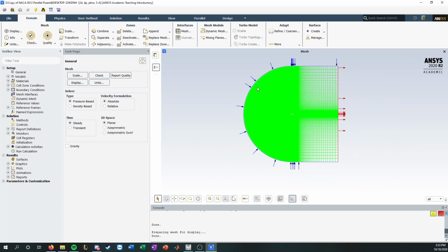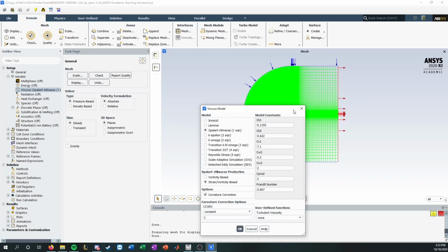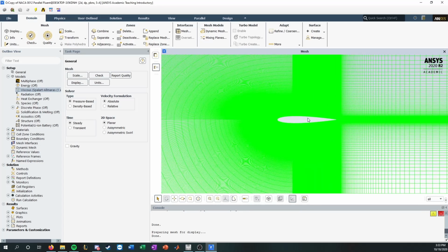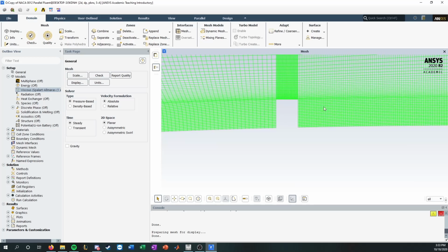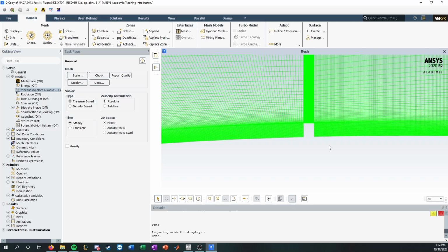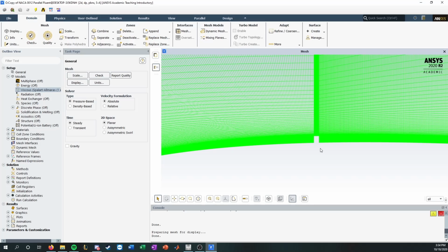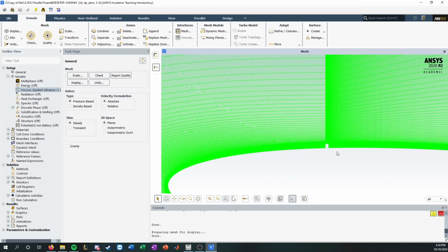and the other part is simply doing this in 2D. Vortex generators, as I've said, are three-dimensional effects, and in Spalart-Allmaras, or really in any of these models, you're going to hit something and it's not really going to capture vortex. It's not going to create a vortex. You might have a trapped vortex here, and that's going to be something similar to a wall or a step, which is the traditional wall-bounded flow. So you will see a small recirculation zone.